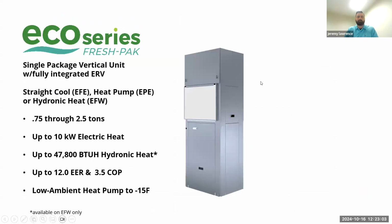And that's the Fresh Pack. So the Fresh Pack is 3/4 ton all the way up to 2.5 tons. So one unit ducted can do a full townhouse, or each quad could get its own, or through the ATS SpecTool, we have quoted 40-story buildings where each unit has its own control. Up to 10 kilowatts of electric heat, up to almost 50 thousand BTU of hydronic heat, and 12 EER, 3.5 COP on the heat pump. Low ambient heat pump down to minus 15 degrees Fahrenheit.